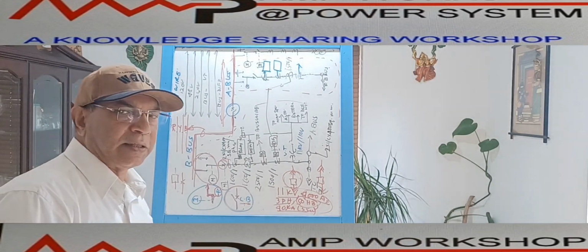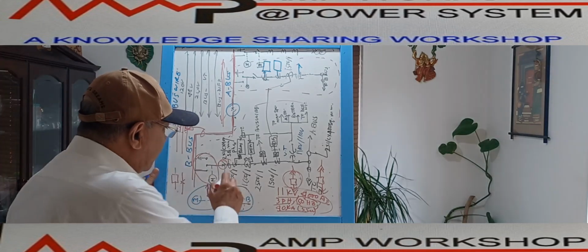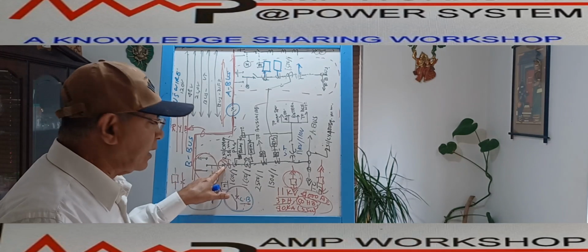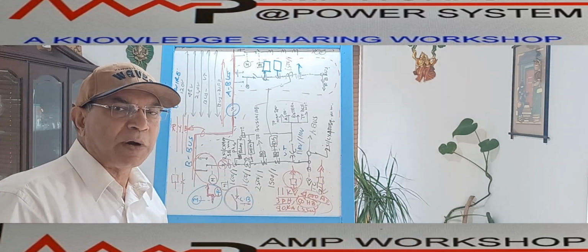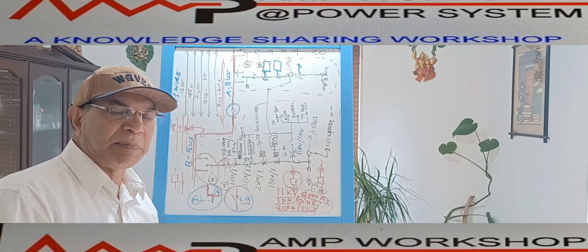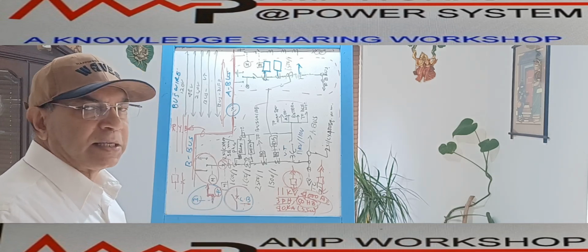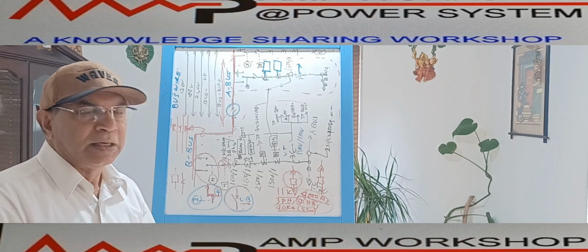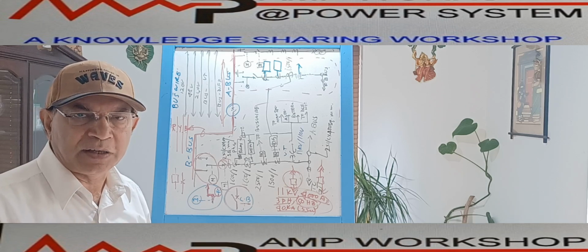After the circuit breaker, this is a bus bar coming. We have already discussed the isolated and disconnected positions, connected on the bottom part of the circuit breaker. From there a bus bar runs. Over the bus bar, various sensing devices are located. What are the sensing devices? The sensing devices are various CTs and PTs.